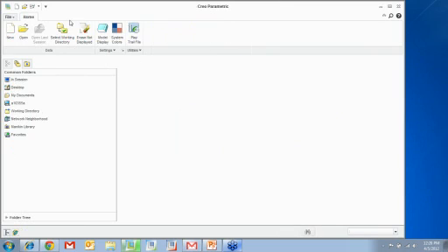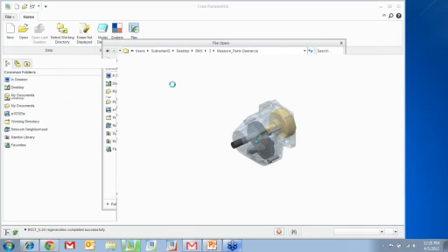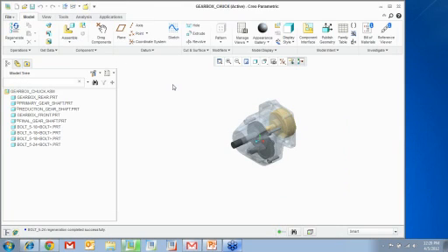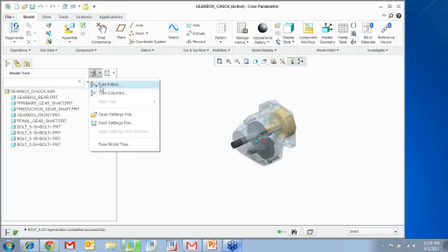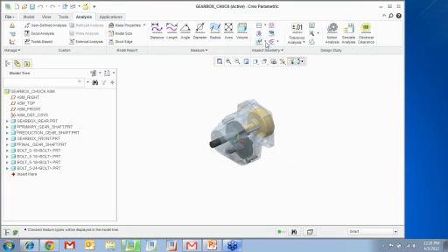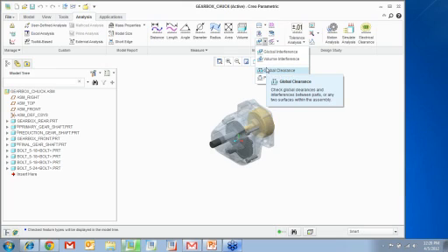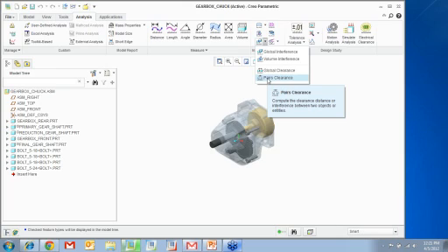All right. So next thing we're going to talk about is clearance. Let's look at a pairs clearance example. I want to know what is the clearance between two parts or two surfaces. So I'm going to get the features shown up in the model tree, go to analysis, and right here you have global interference, volume interference, which tells you if there is anything else interfering with the closed quilt. You have global clearance, where you can check clearances or interferences between parts or any two surfaces in an assembly, or you can do pairs. You just pick a pair of parts and see what's wrong with that.